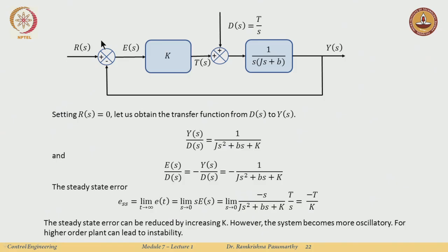Now, E(s) because of D(s) just becomes the negative of y. So y goes here, there is no r. So E(s) is simply the negative of y. I can also see what is the effect of the disturbance on the error signal. It is straightforward to see, because we just compute this with R(s) equal to 0. There is nothing here, Y(s) enters here. What is E(s)? E(s) is 0 minus the signal that is coming here. So E(s) is the negative of Y(s).